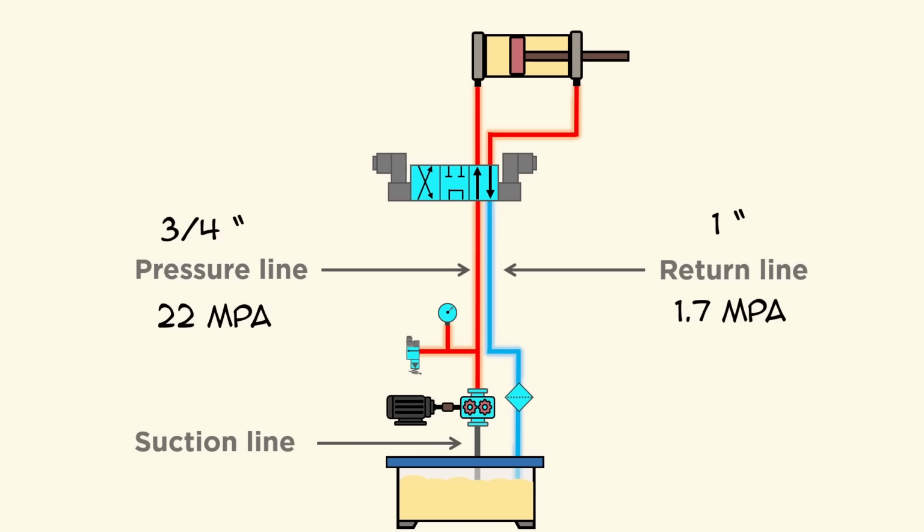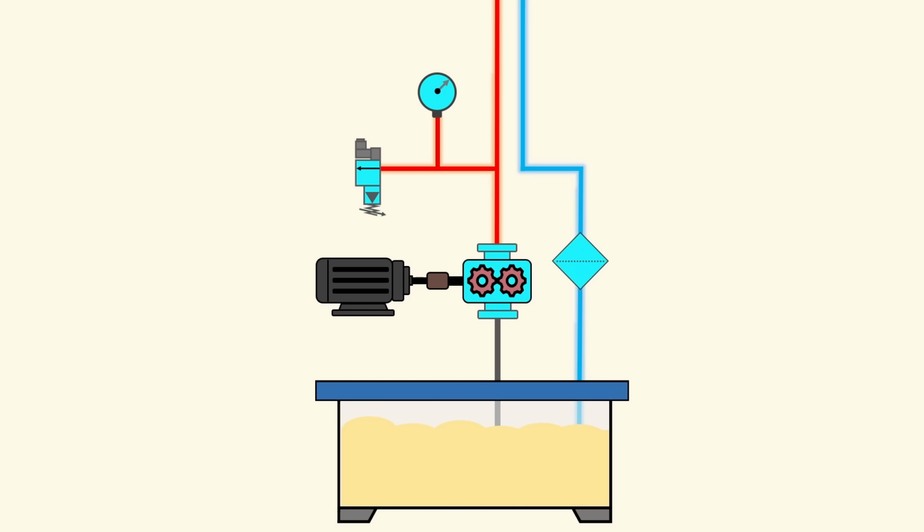Now, the most critical hose line in any hydraulic system, the suction line. And the suction line hose sizing needs a deeper understanding of how a pump actually works. We all believe the pump sucks the oil from the tank, but this is not true. In reality, the oil is pushed into the pump by the atmospheric pressure, and that makes the suction line sizing extremely critical. So I will cover suction line sizing in a dedicated separate video.